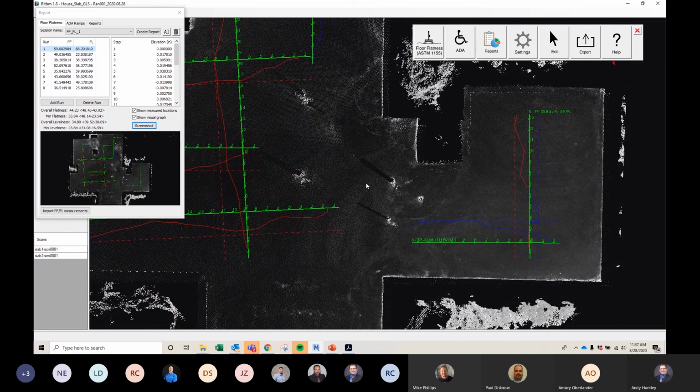A lot of times on a construction site in concrete, we're kind of at the mercy of where you want to scan a high-rise deck. You want to scan it as soon as that concrete is able to walk on, because at that point, they're not bringing a bunch of stuff in. But if you miss that window, you're going to have a lot of items on your deck that you're going to have to clean out.